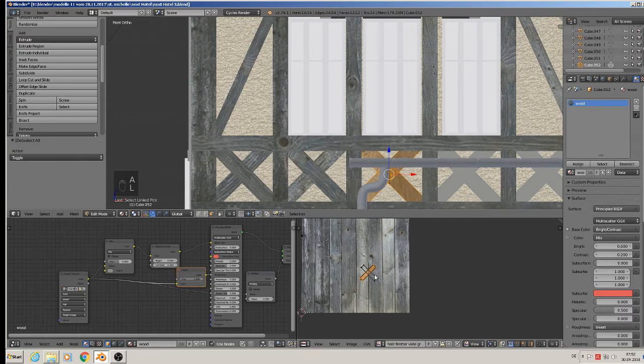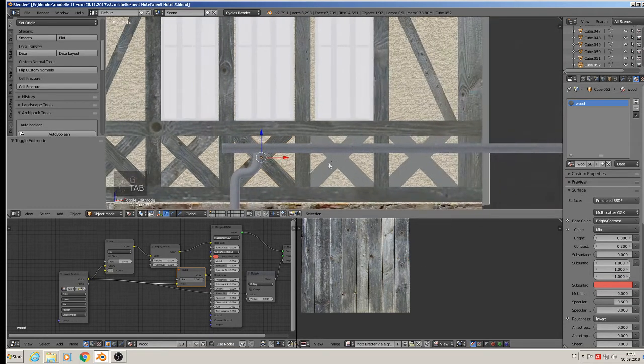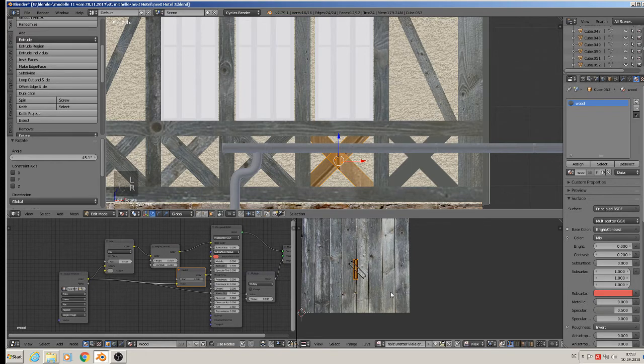A to deselect, L to select one, scale them up, grabbing, positioning, get the other one with L, rotate, and so on. You can handle each word here as you want. That is, yeah, like the modeling, but it is for the UV. And it is 2D, not 3D. That is the difference.